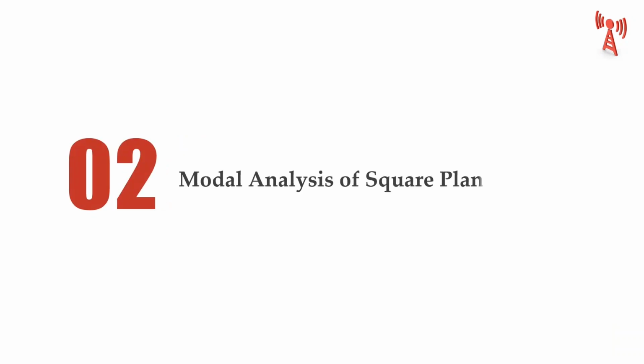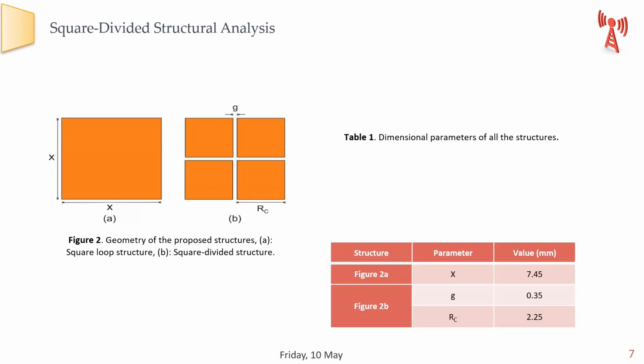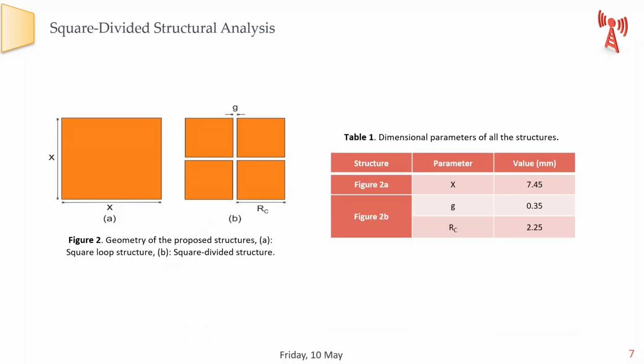Now we move to the second main section, where I will present all the results obtained from this work, and I will start with the first study. Our research methodology focused on analyzing the characteristic modes in a free space environment and evaluating the characteristic angle, quality factor, and radiation pattern for each individual radiating mode within the frequency range of 20 to 44 GHz.